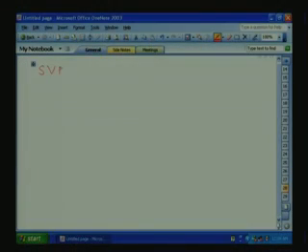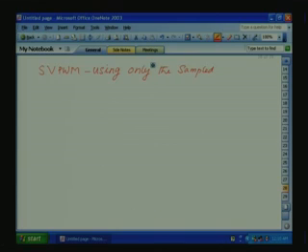In this class, we will try to learn a technique to implement the space vector based PWM based only on sample reference phase amplitude. So, we will study a simple technique, that is SV PWM using only the sampled reference phase amplitudes.